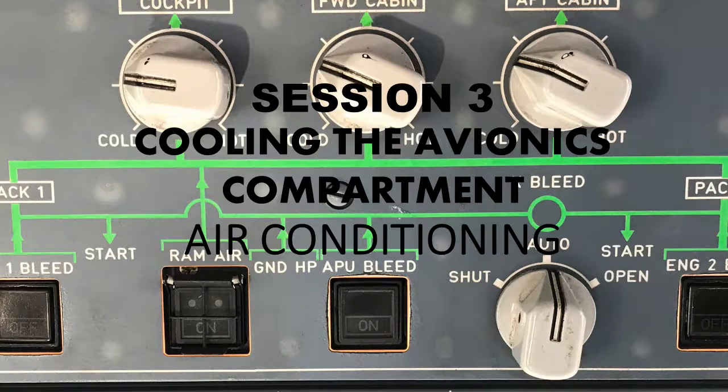Okay, so it's a butterfly type. Just so you know, there are 2 micro switches that are going to signal the valve position to the avionics ventilation computer, and the valve is located under panel 128EG in the avionics compartment. It's the forward part of it.